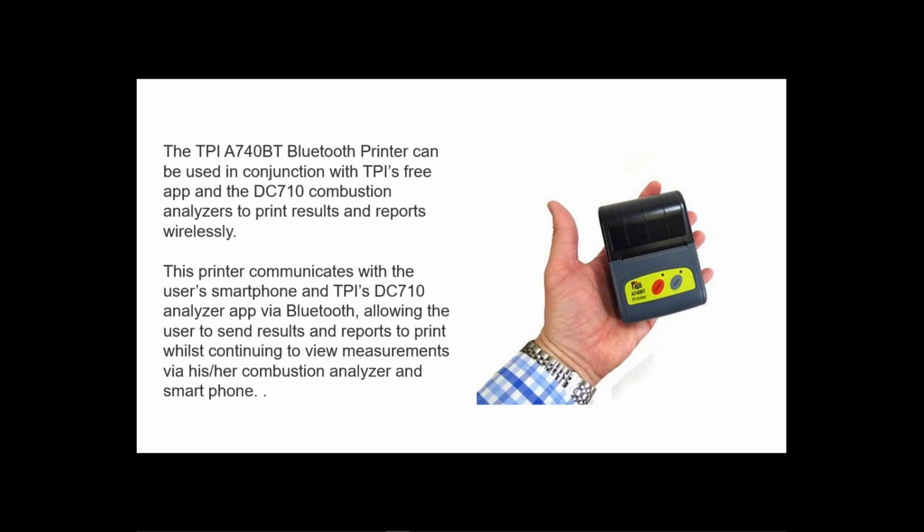You may get to the point where you're looking on your analyzer, you're in front of a burner, you turn in that screwdriver, you like those numbers, they all look good, print. And then at some other point, you may say, well, let me make another adjustment. Well, your analyzer is still running. Your printer is still there. You can make any adjustment you want, print as many times as you want, and file as many times as you want.